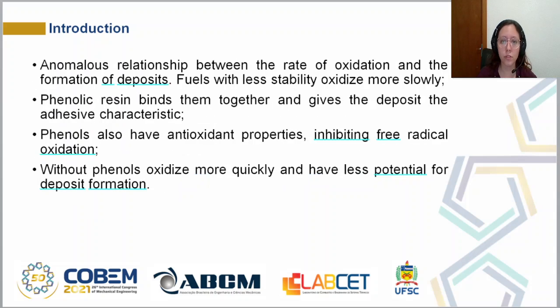There's an anomalous relationship between the rate of oxidation and the formation of the deposit. That's related to the phenols, which provide a resin to bind the insoluble materials in the fuel and have antioxidant properties.